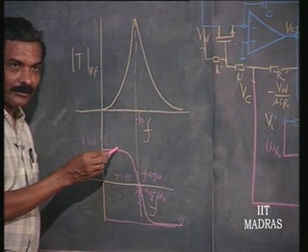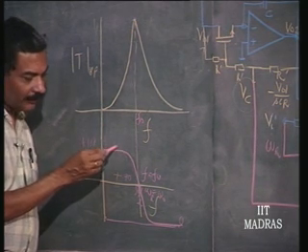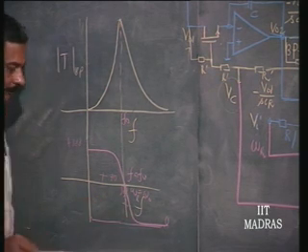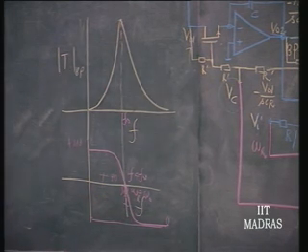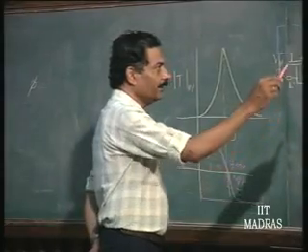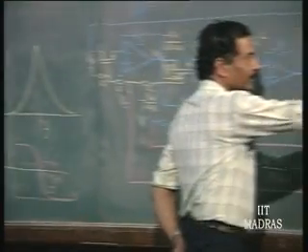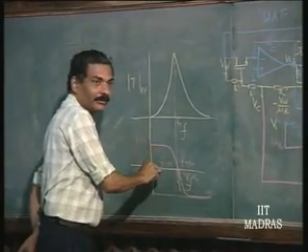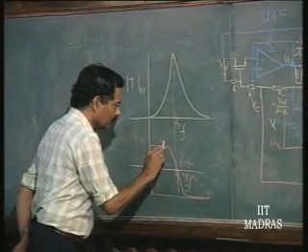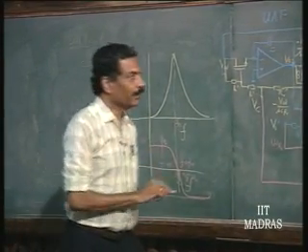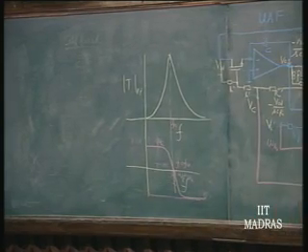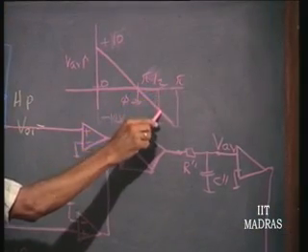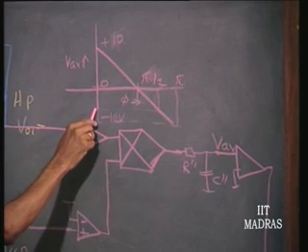This is important, it is changing from higher phase shift to this. Now, as far as the phase detector is concerned, if the phase shift is closer to 180 degrees, we have started with omega r less than omega naught, omega r somewhere here in this region. When the phase shift is greater than pi by 2, you are getting a negative value.